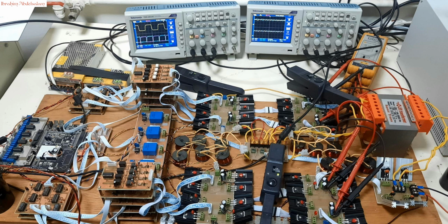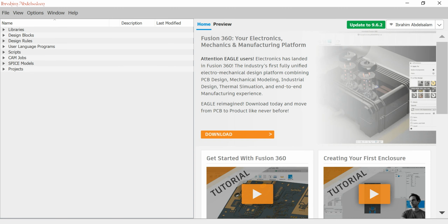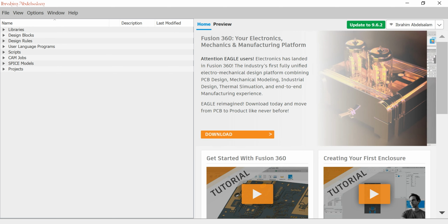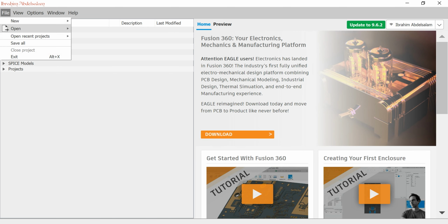This is exercise number 2 in PCB design using Eagle. In this design we will build a 12 voltage, 5 voltage and minus 12 voltage power supply, and I will show you more new tricks. Let's open Eagle, and this time I will use Eagle version 9.6. Open, File, New, Schematic.